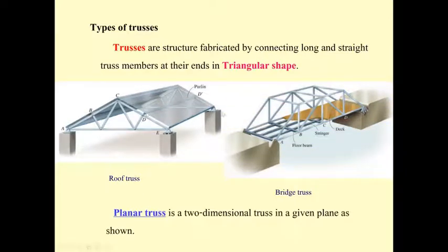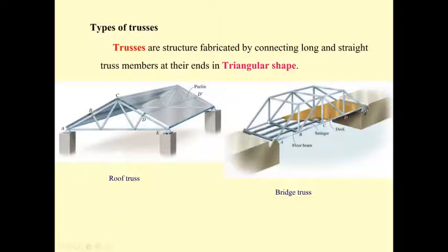Okay, and also the bridge truss. When they finish building all the foundation, and while building the foundation, they fabricate the truss in the area nearby, and then they use the crane to lift each truss, put the trusses onto the foundation, and then they link each truss by the floor beam.